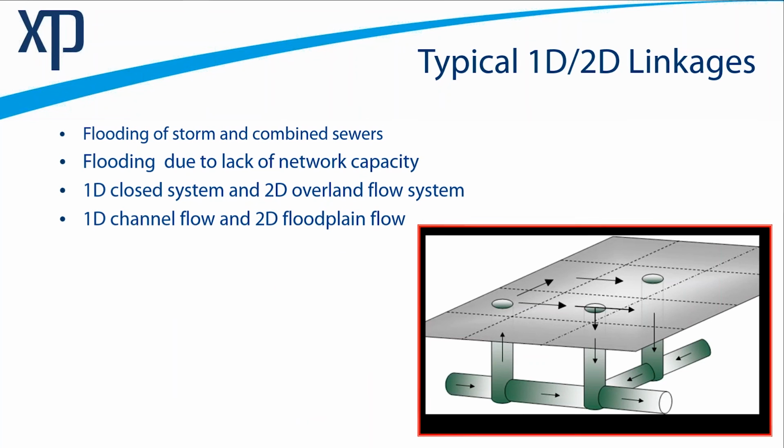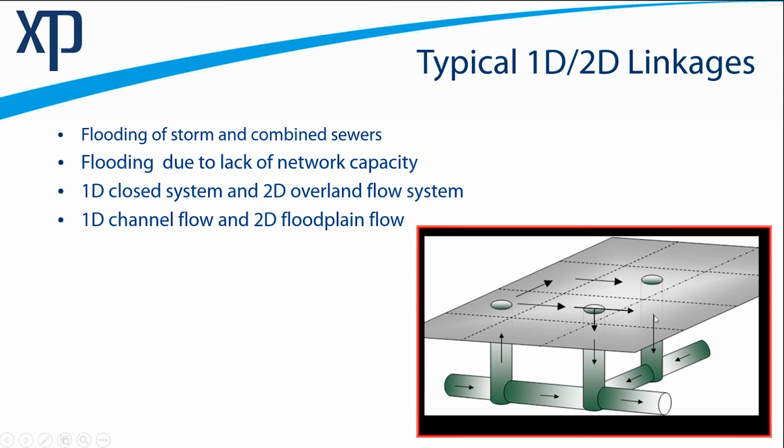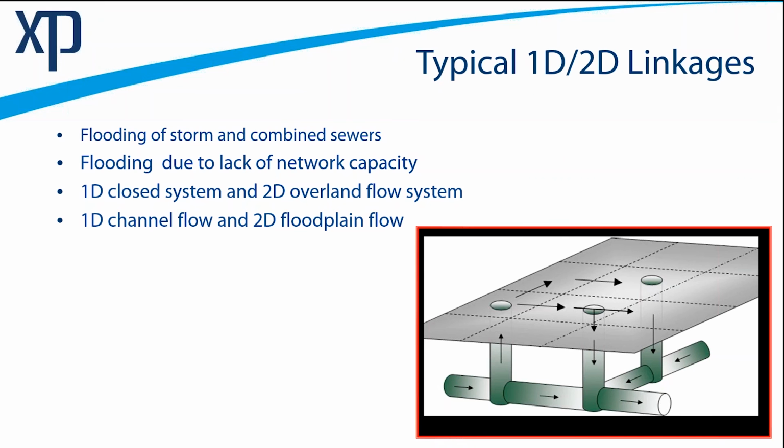So when that linkage happens, let's say for a manhole, let's say you've got a storm or combined sewer, and you've got essentially a case where water could surcharge in the manhole. It could reach the surface. It could then flow over land following the terrain. It could find manholes to be captured into. But you're also allowed, as you've observed in the real world, that an inlet might have some bypass. Perhaps you're capturing some and bypassing others.